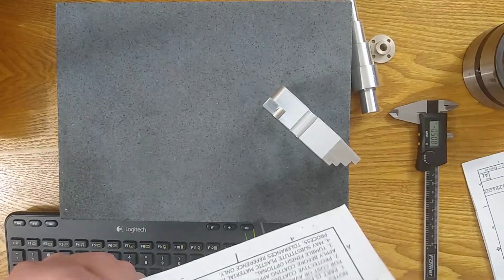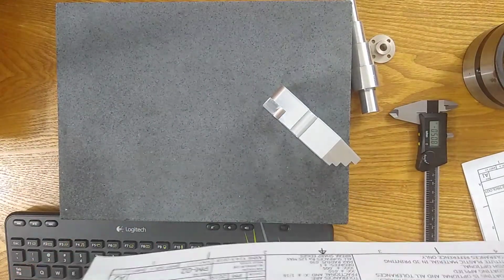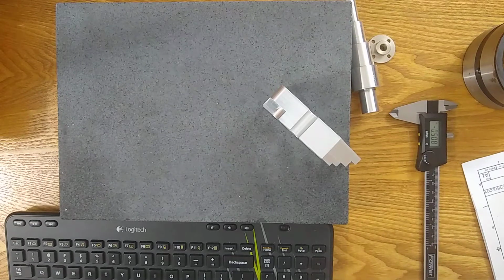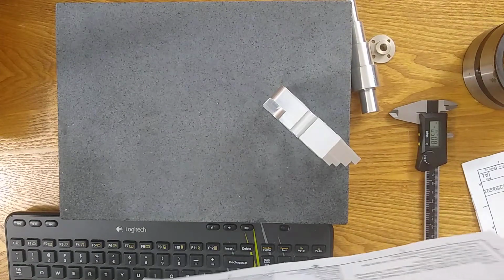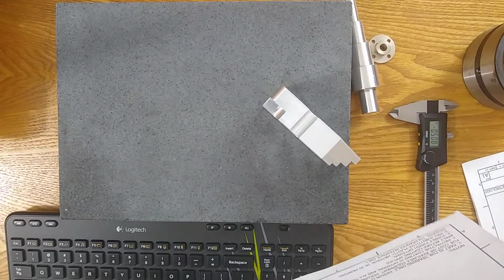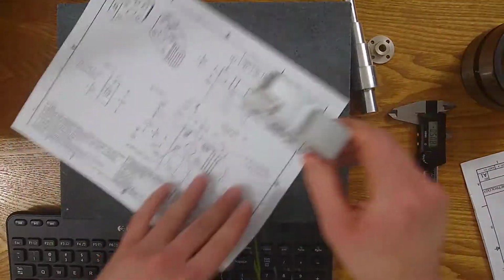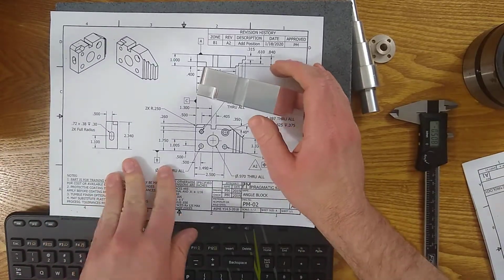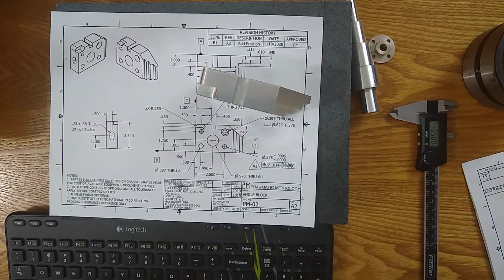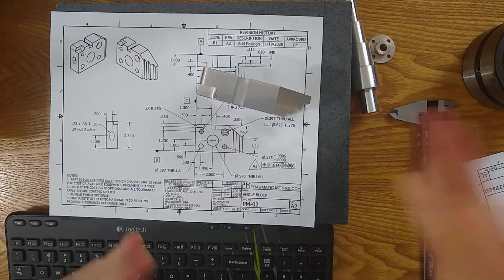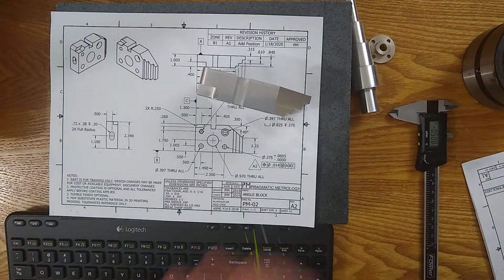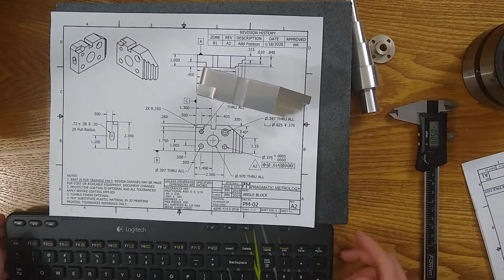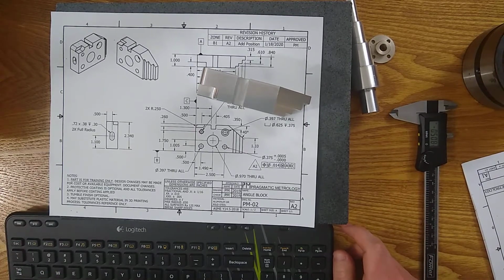If we were talking about this print, for tapped hole depth you generally want the most tolerance because it's hard to control, and functionally, does it really matter how deep a lot of the threads go? It doesn't usually matter how deep the bolts or the screws go. So generally, you'll see your biggest tolerance might be the fractional one, a 16th. Usually that's like a rotation of the tap, which is what the machine can control.